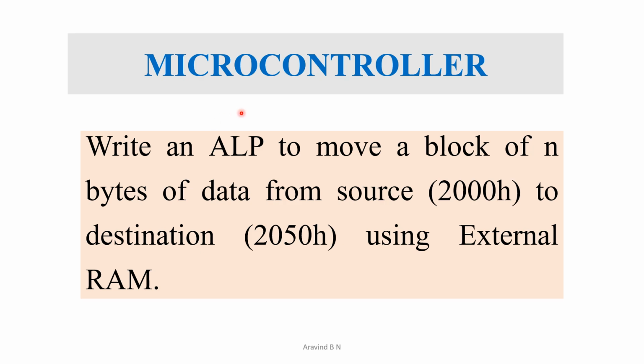In this session, we are going to have one more program of 8051 microcontroller. The program is: write an ALP to move a block of n bytes of data from source, that is 2000H, to destination, that is 2050H, using external RAM.